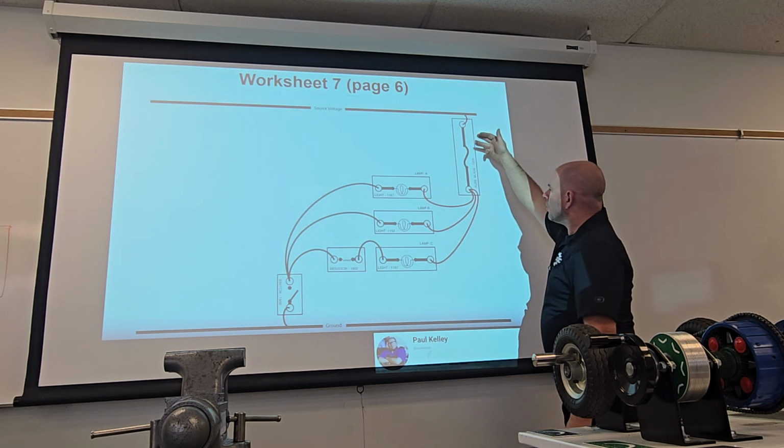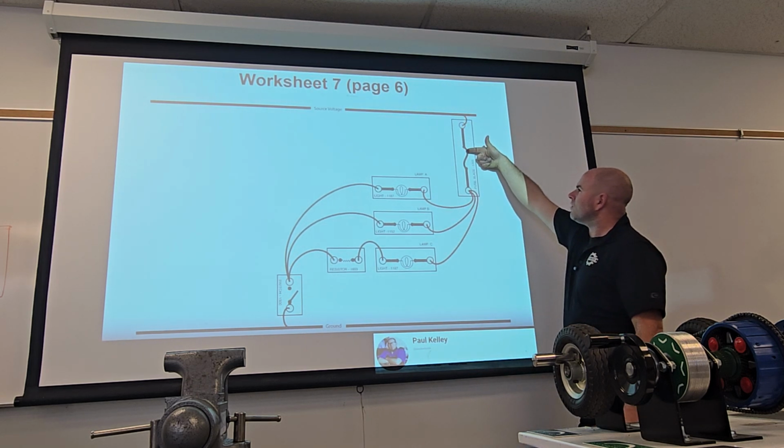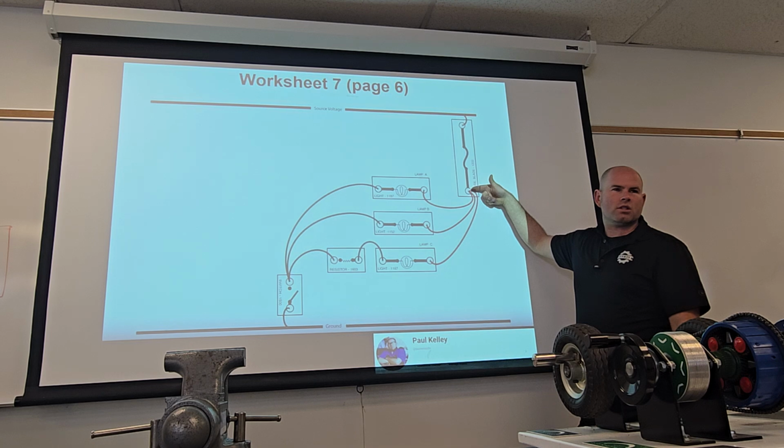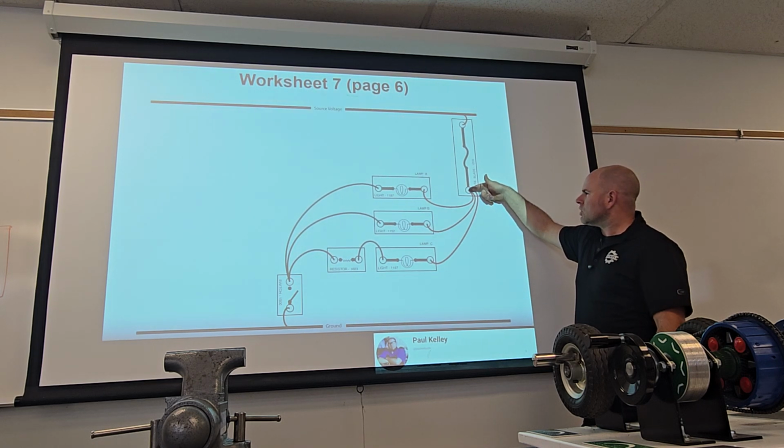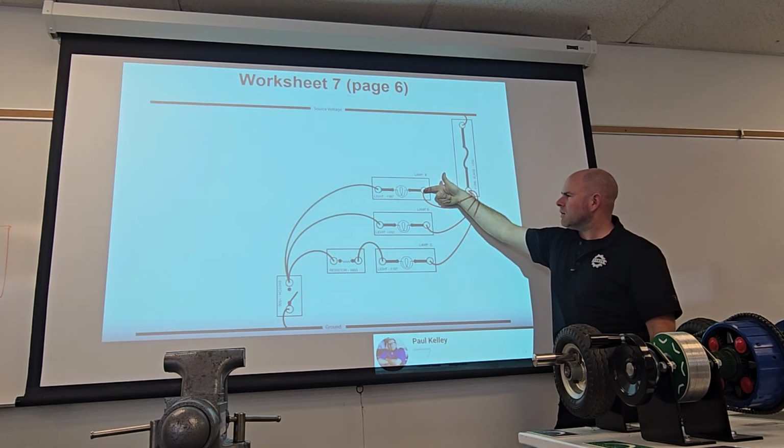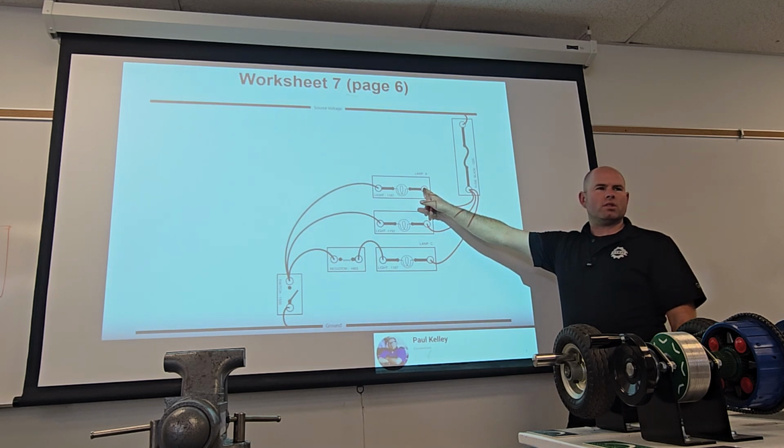Because if you look, we agree, there's 12 volts. 12 volts goes through the fuse. Should we lose any voltage through the fuse? No. Not really. Should we lose any voltage through the wire? Not really. So we agree we should have 12 volts here.